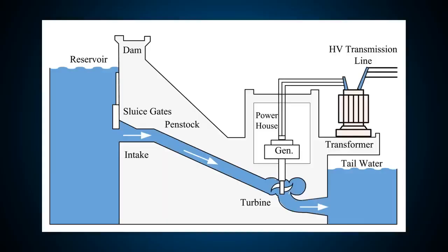Hydroelectric plants generate electricity like fossil fuels and nuclear power plants, but spin a turbine using the force of water instead of steam. A hydro plant uses the pressure of water created by either a difference of elevation for dams or the force of water in rivers. In either case, the head pressure can be regulated by a control gate, so when the water flows down a controlled pipeline called a penstock, the pressure builds up, spinning a turbine at the bottom and turns the rotor of an AC generator.